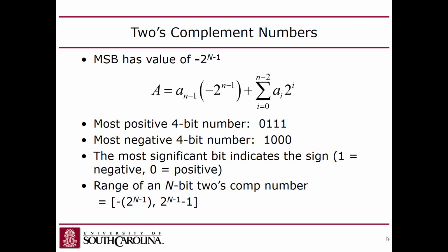What I used to do was I would just take the 2's complement. So I know it's negative. If I take the 2's complement, it'll make it a positive number. So, invert all the bits. It makes it 4. That's the 1's complement. And then you add 1, 5. So that's negative 5, right? Makes sense? That's what I used to do.